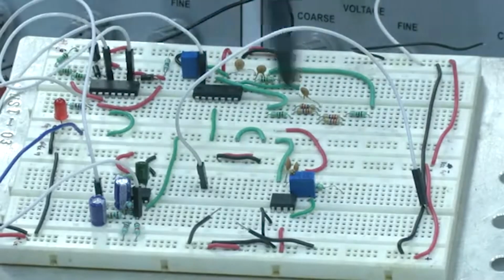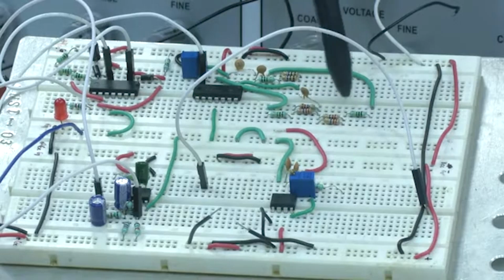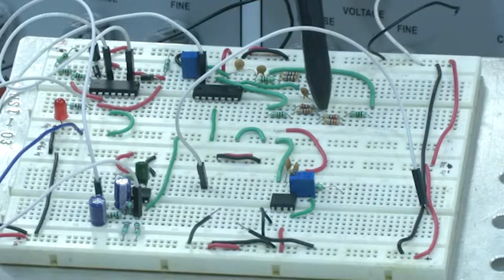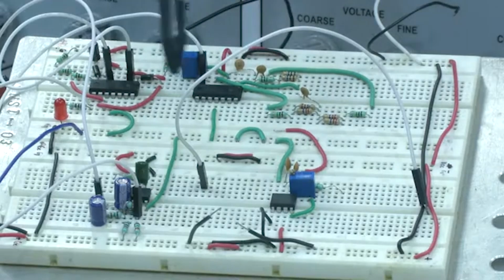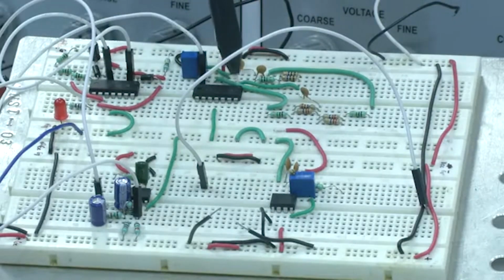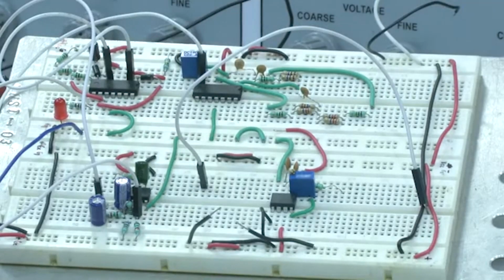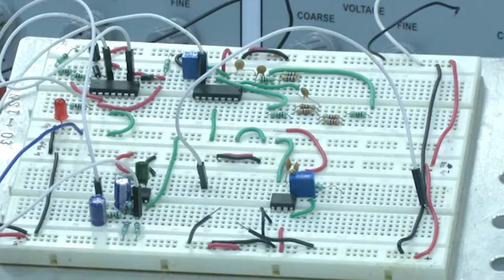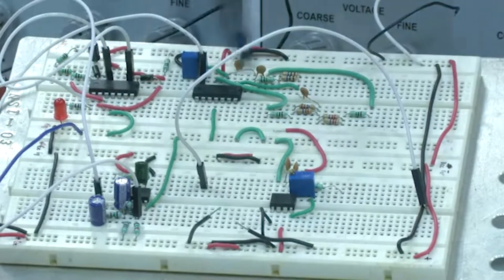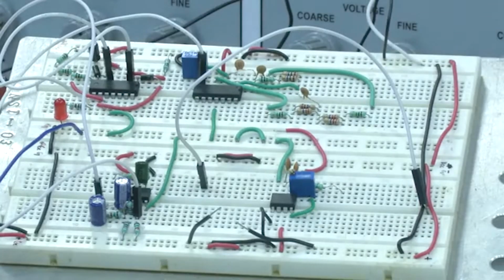If you observe at this point, we have different resistors connected in parallel, right, and connected in series, series, parallel, again parallel and series, and the capacitor, and both the op amps we are using are from TL084. TL084 is a quad op amp, so it has 4 op amps inside. We are using only 2 op amps in this case, and this is another part where, as we have seen even in the simulation, we are shifting the phase value or shifting the narrow band, right.